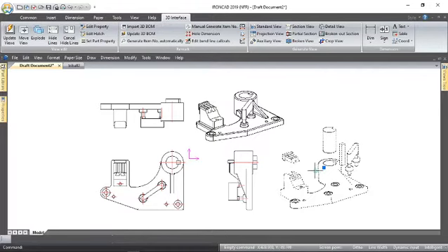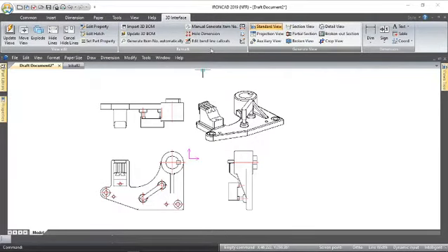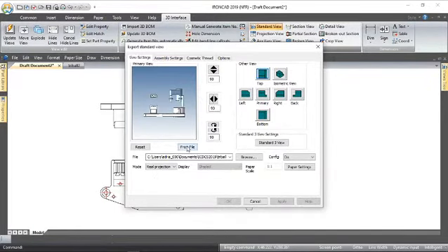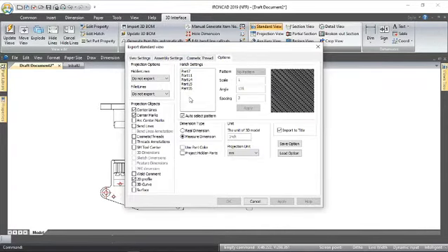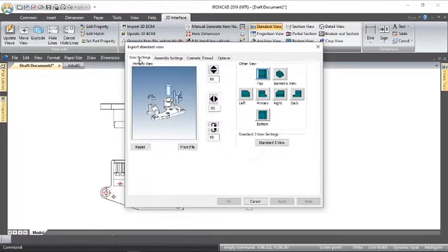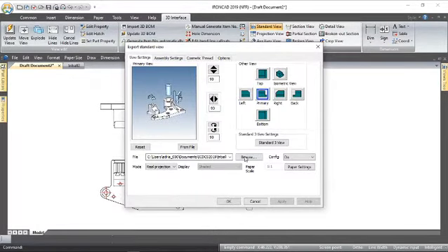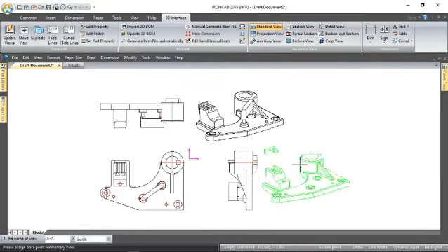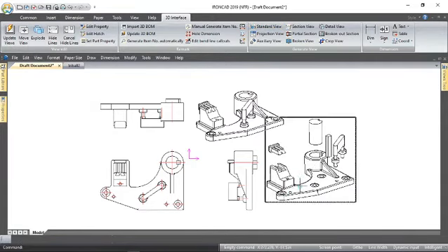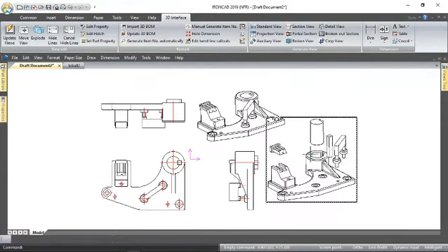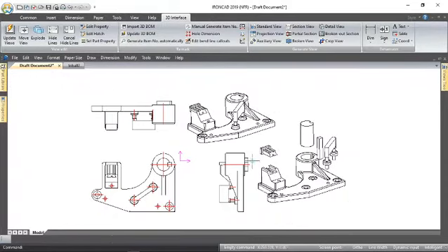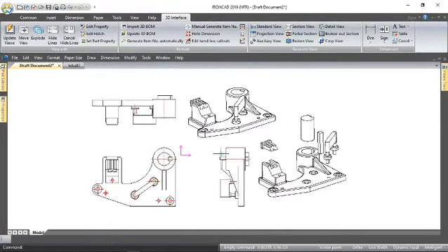In actual fact what I'll do, I'll just redo that, because standard view, I'll do from file, and I'll go to options, and I'll say export all the lines, all the fillet lines, view settings. From that, click on the primary view, go OK, and basically now you can see the fillet lines on that exploded view as well, like so. So that's how we do that.